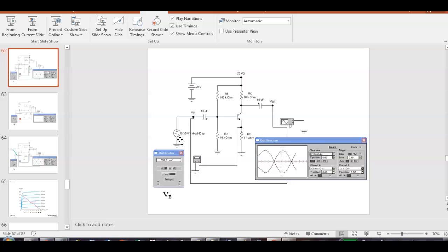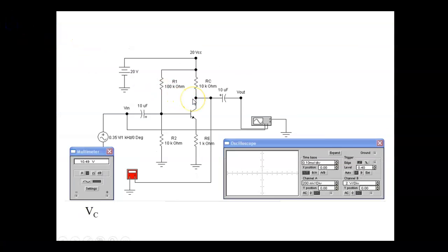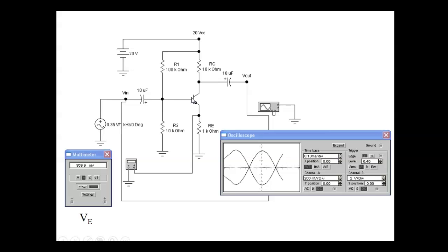And if we got a low output impedance, that works. So to get maximum power transfer in all these amplifiers is very, very hard, because not only are we dealing with standard resistors, we're also trying to match impedances between input and output. So design of these guys is not easy, guys. But we're not trying to teach design.